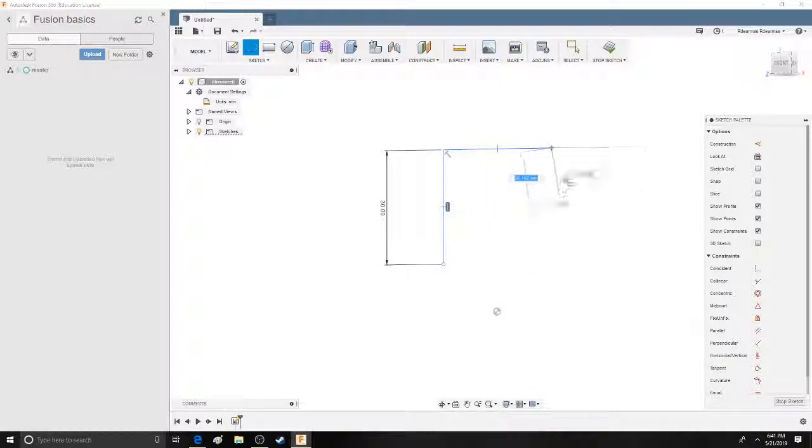So what I just did right there, this is a good time to explain this. From this singular point up here that we just created by clicking a sketch, we can drag down a line and move it in any direction. Once you have a point anchored, you can move it anywhere you want. You also get the measurements and the degrees for it, but there's a special little trick you can do. If you want a point to be fixed to yours, you can attach it to it, and it moves downward with a blue dotted line, and it allows you to put it exactly next to your current design. It even tells you that it is right there on the same level as it.